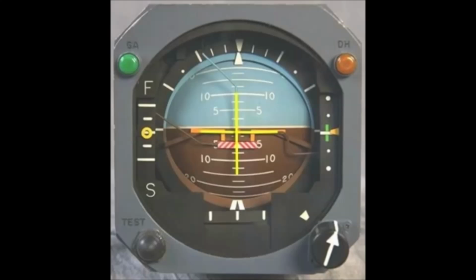If the symbolic aircraft is above the horizon line, the blue background, the aircraft is nose up. If the symbolic aircraft is below the horizon line, the brown background, the aircraft is nose down. Because it is the horizon that moves up and down and turns, while the symbolic aircraft is fixed relative to the rest of the panel, trainees get confused. A standard corrective given by flight instructors is: fly the little airplane and not the horizon.